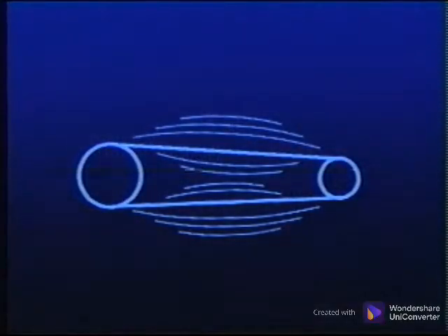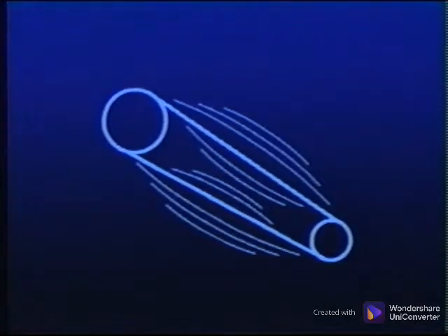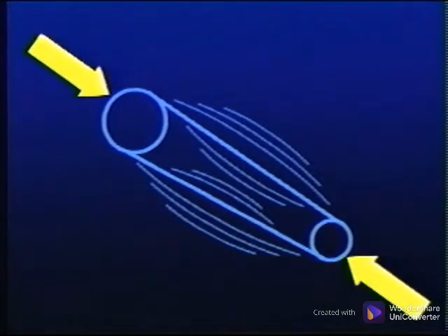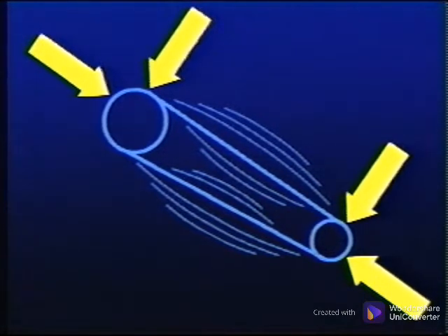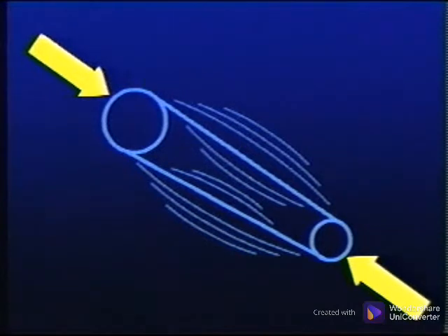When the center lines of the motor and driven equipment are in the same horizontal plane, there is no change in the measurement locations. When the shaft center lines are not in the same horizontal plane, 1 radial measurement should be made in line with the centers of both shafts, and the other should be 90 degrees to it. This inline measurement is also the direction of belt tension and is used to indicate eccentricity or excessive runout in the sheave as well as a bent shaft.